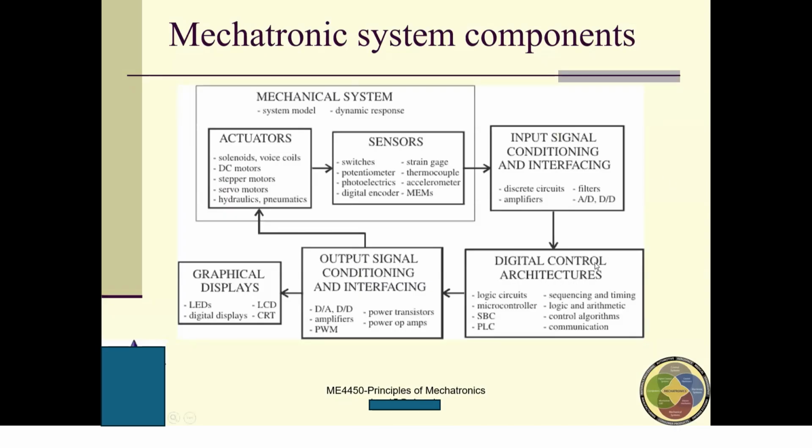So the microcontroller, the digital control architectures. There are logic circuits, microcontroller, SBC, PLC, and SBC is a single board controller. PLC is a programmable logic controller. Microcontroller is the more general one. The single board controller is a very early version of the microcontroller, about the 1970s. I want to tell you the history, but we are going to focus on the microcontroller and PLC. Actually, PLC is a specialized microcontroller.